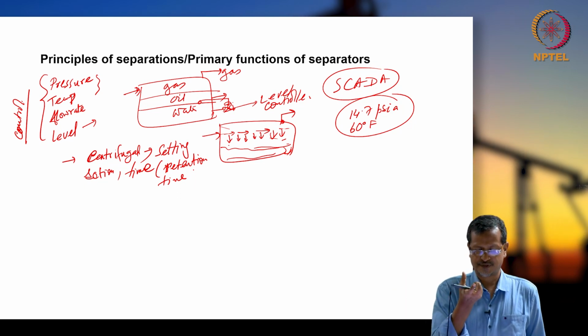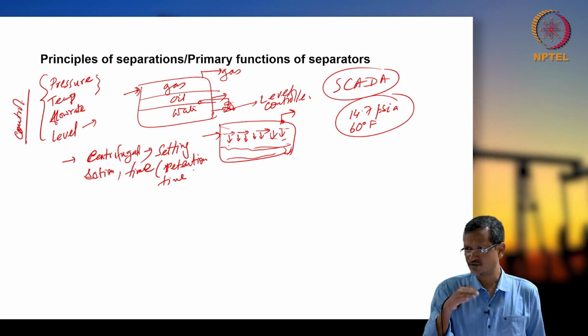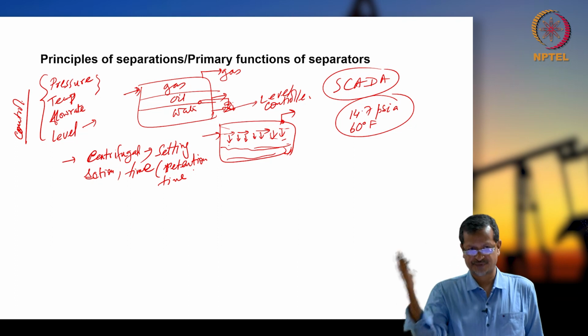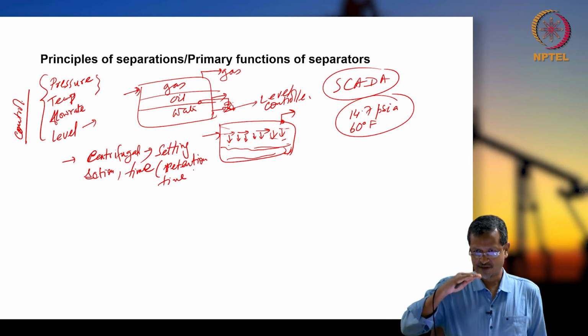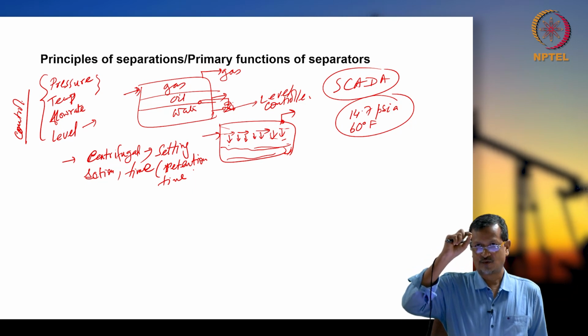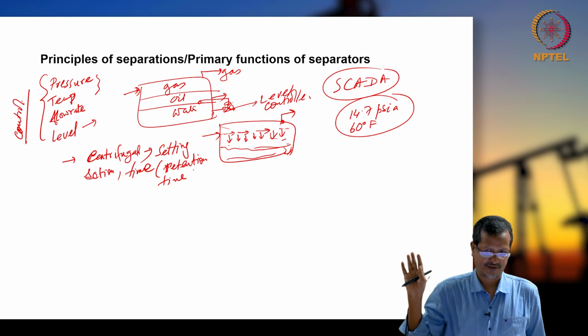So the particle settlement time is not enough. In that case you will not get proper separation. If you give a longer separation time, 1 month, 2 months, 4 months, it will be very good separation. Slowly oil particles will move up from water, and water particles in oil will also move down. So separation will be very nice, life is beautiful.